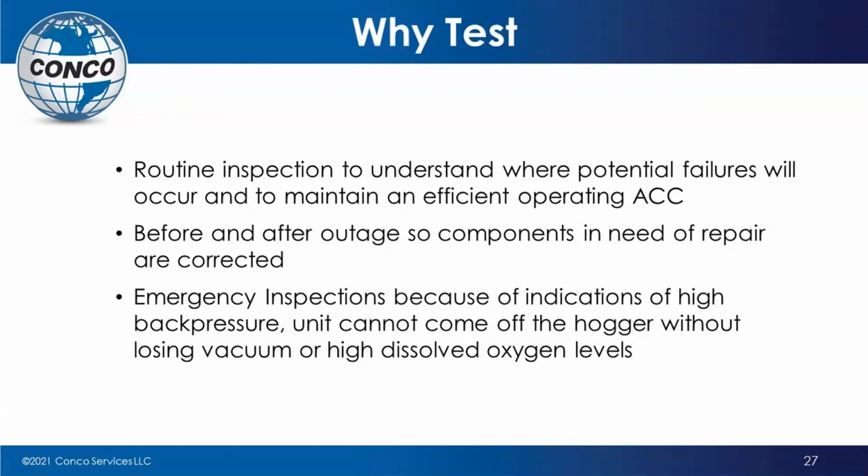On the other side, when you come out of these outages, after you've changed gaskets and changed valves and you've removed bolts and torqued them back up, maybe it'd be a good idea to do a test then to make sure that everything you've done is buttoned up tight. Because if not, it's going to raise its ugly head when you start that unit up and start pressing hard. And sometimes it'll show up right away. And trust me, when it does, that's the best time because you are not under the gun to give them all the megawatts you need.